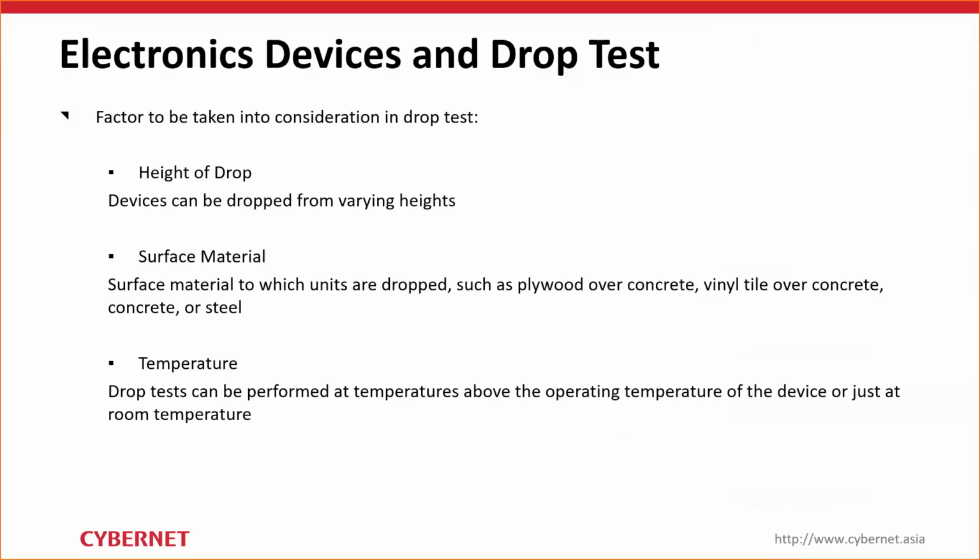Drop height can be specified with the inclusion of standard Earth gravity quite easily. The surface material can be modeled, and different surface friction can be specified. And the environment temperature of the drop test can be set to whichever temperature you desire, depending on the application you are trying to simulate.